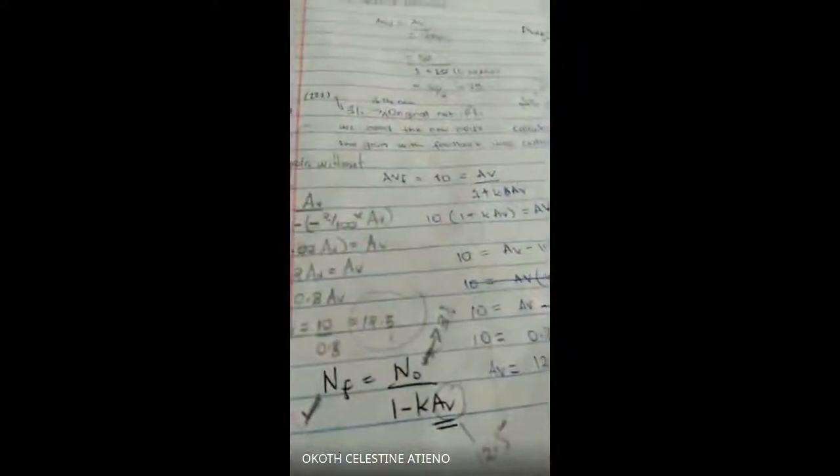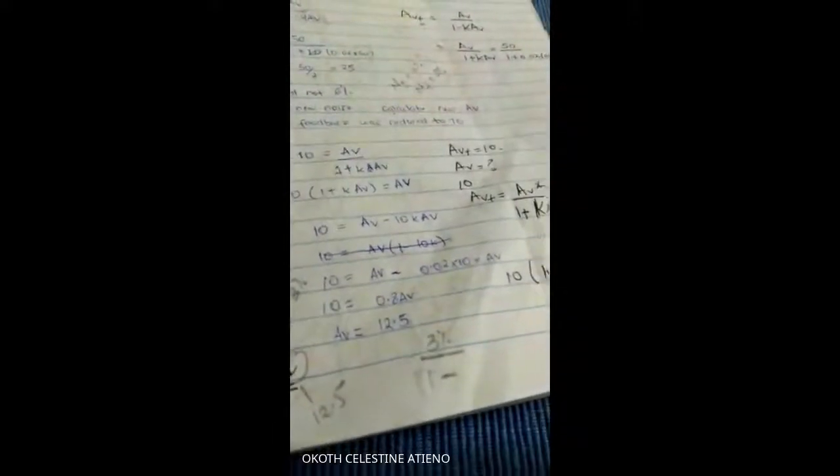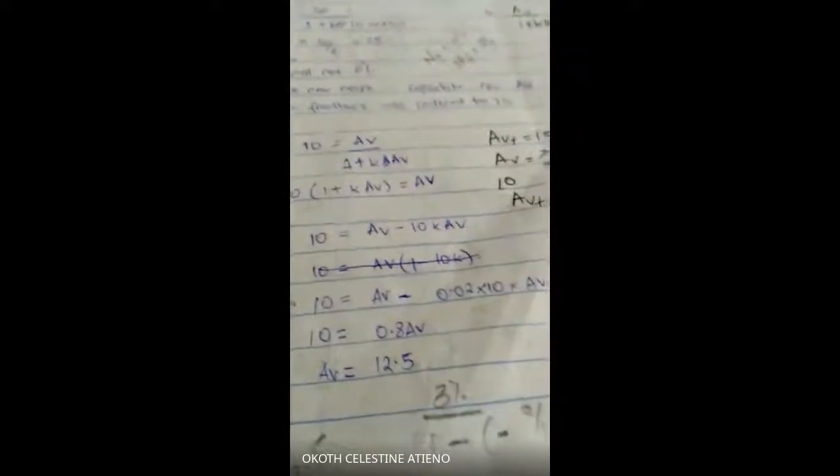So here is where we'll use that 12.5. That's why we calculated it. We've said our original value now will be 3%, which we got from the last question. So we'll have 3% into 1 minus K, of course K is negative. So this expression will be 3% over 1 minus K, minus 2 over 100 times 12.5. If you calculate this, you'll get your answer. So that will be your gain with feedback.